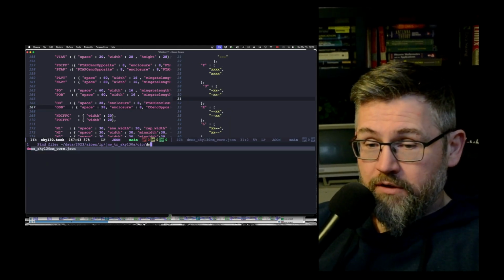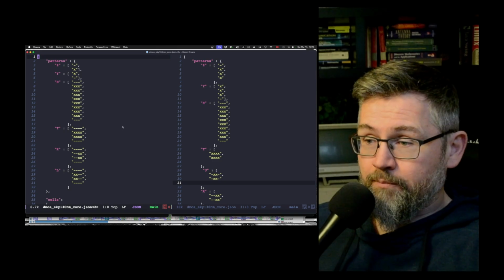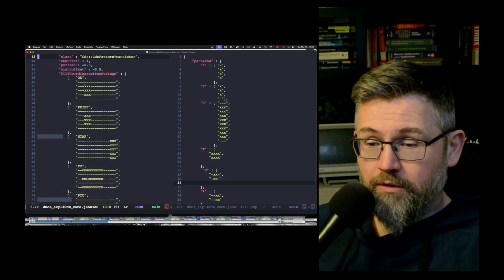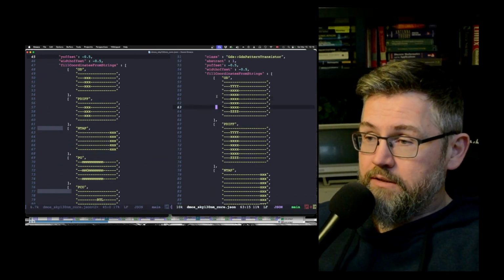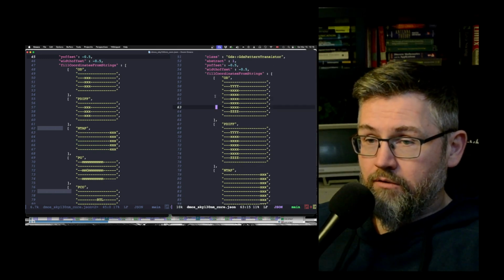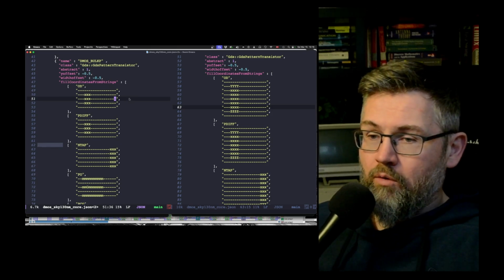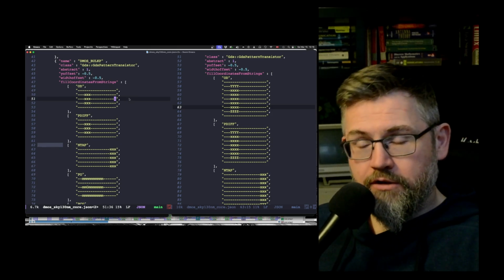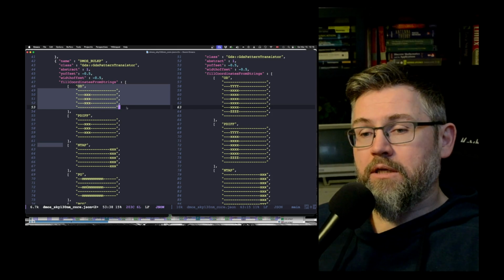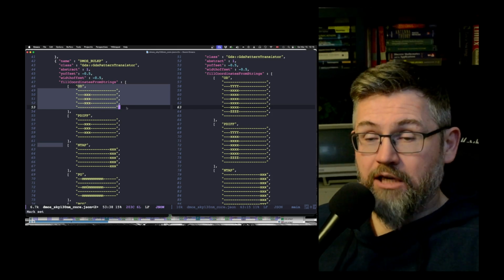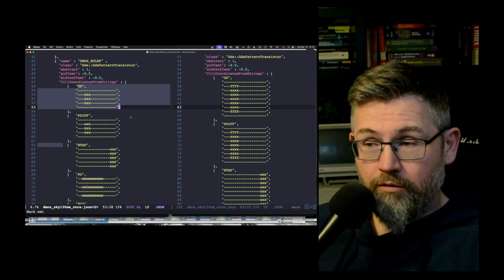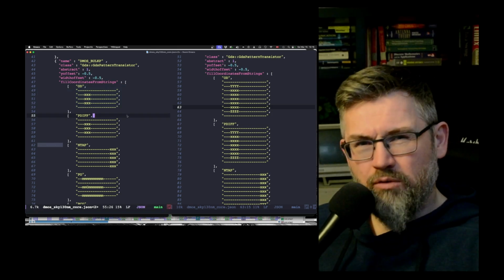So if I open up this DMOS file between the two, the first here, ignore that, there's details, but this is the ASCII art I talked about. And as you can see, the ASCII art is different. So I've had to modify and change how the transistor is generated for SKY130 on the left side. That, by the way, took forever.